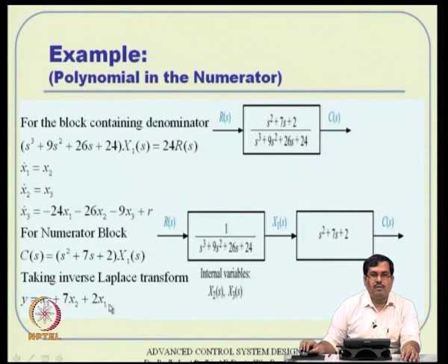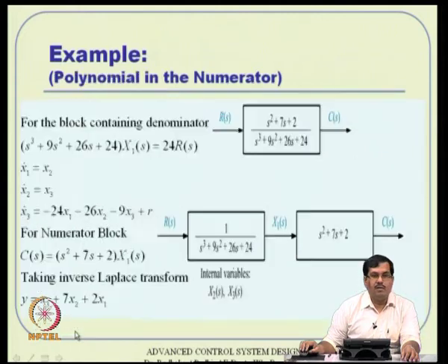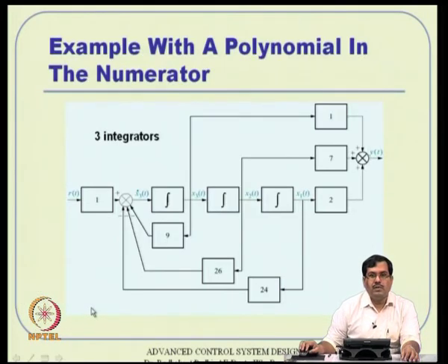So, the state equation and the dynamic equations remain the same, but the output equation takes this form. Earlier, remember, it was just x1. Now it is not only x1, but it is like this. How to realize this? Again, the bottom side of the story remains the same, because the state space realization remains the same. Then for the top side, you take these branches out here.